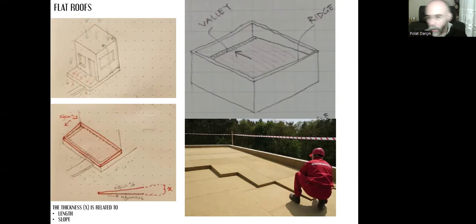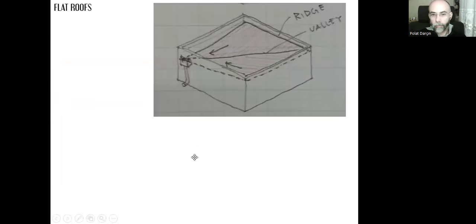In this example, you are seeing a specially produced rockwool, which is enhanced against water damage. It doesn't get wet, and it's not affected negatively if it's wet. Instead of creating a long channel, we can collect all the water at a single point using a point drainage like that. For this, we need to create two sloping surfaces, and their combination will create a valley.